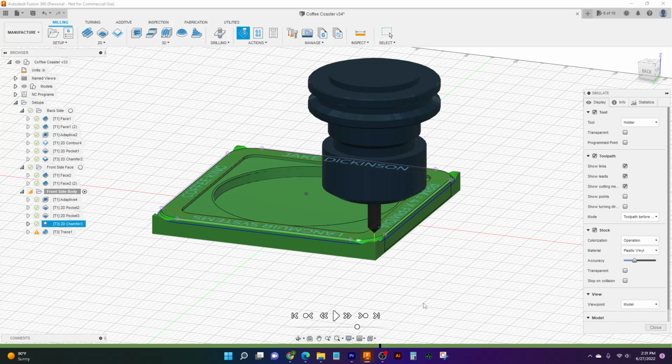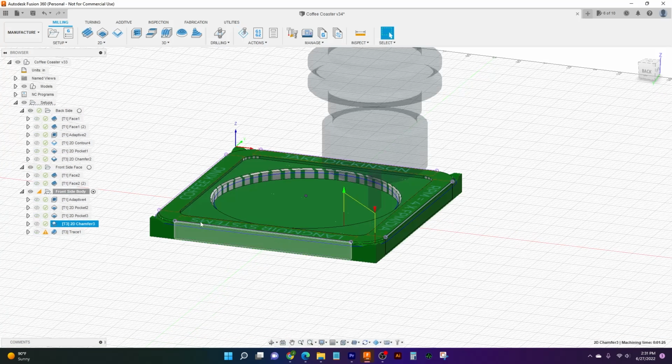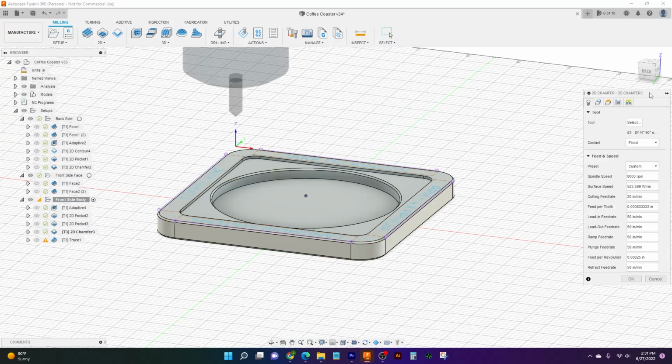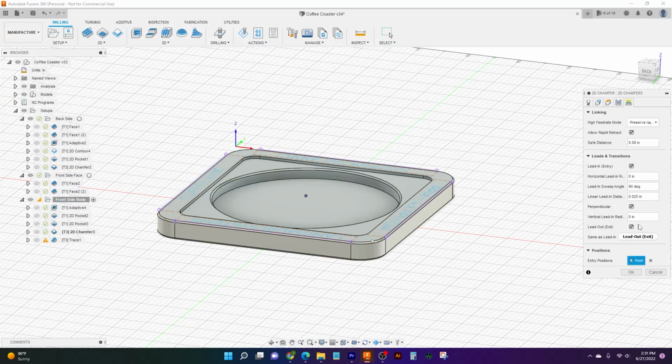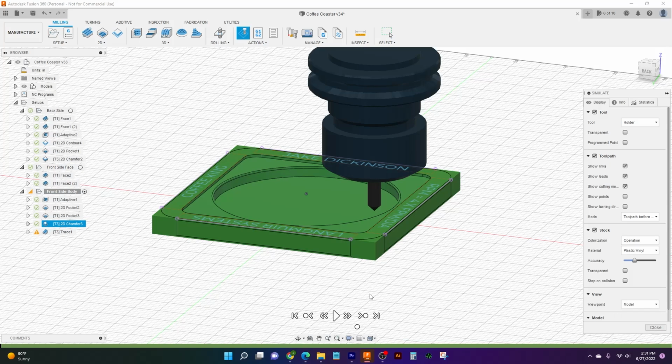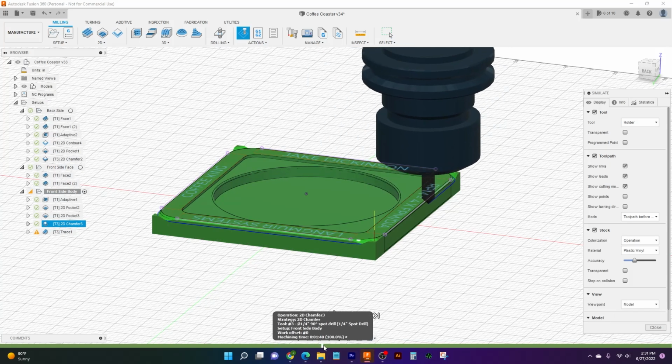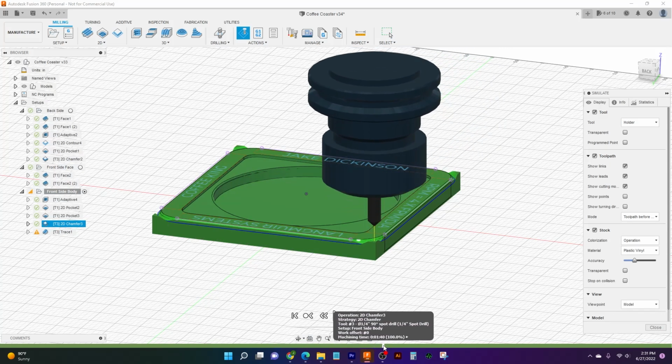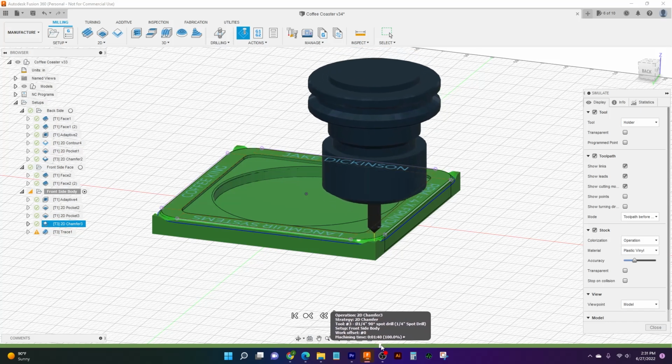You can actually pick, let me just detour a little bit into our linking. This is a position, so we can pick our entry position. What I've done is I've selected entry position and picked on a radius. Wherever I pick here, that's where it's going to come in at. So we'll go back to simulate. I'm just going to drag it across, and there it comes in and out right where I told it to.